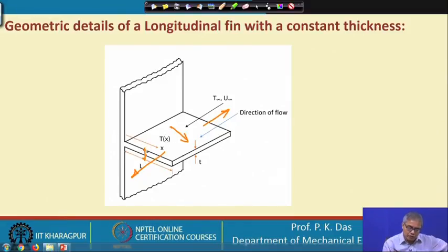So, basically this direction no temperature variation, this direction no temperature variation, this direction no temperature variation, only temperature variation is along the longitudinal direction. So, this is what we do in fin, and this probably is known to all of you from your heat transfer course.